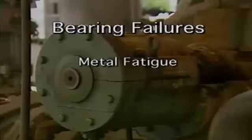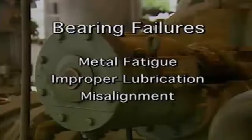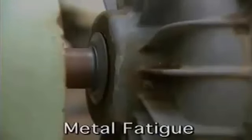A properly installed and maintained bearing can last for years, but eventually bearings fail. The three most common causes of sliding surface bearing failure are metal fatigue, improper lubrication, and misalignment. The term metal fatigue refers to the effect on metal of prolonged flexing and bending.